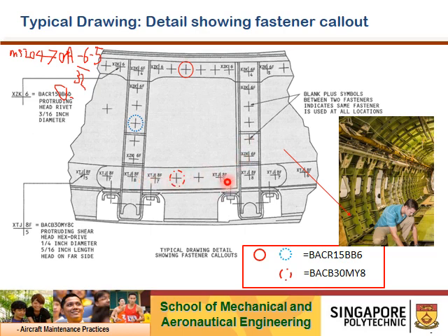So you can see there's an F here. F is referring to the far side. That means when you install the bolt, the bolt head will actually be at the opposite side, and what you see here will be the nut. So that's far side. If it is an N, in this case, I say again, if this is 8N, let me write it down, easier. 8N, if let's say you have this cross and it's 8N and it's XT, same thing, XTJ.